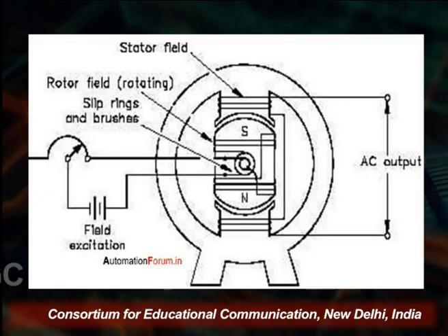It is mostly used with high power generation output, and it involves a DC source applied to the field coils which produces the magnetic field around the rotating element. When the prime mover turns the rotor, the field cuts the conductors of the stationary armature, and the EMF is created in the armature winding. That is what you see on the screen, the AC generator.